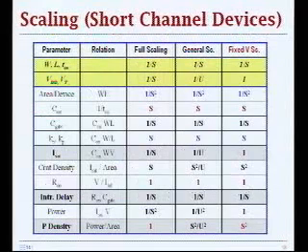Now let's look at a more realistic scaling scenario for short channel devices. From the story that we already presented, we had these different scaling factors. We had fixed voltage scaling, which was good way back in the past. We had full scaling, which is not good for the idea of arbitrarily scaling supply voltages, because that has its own limitations for variation reasons and also for leakage power reasons.